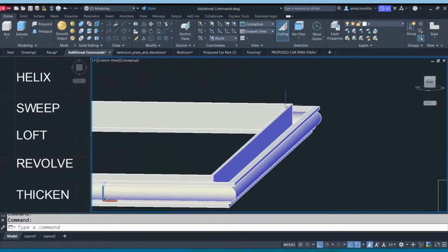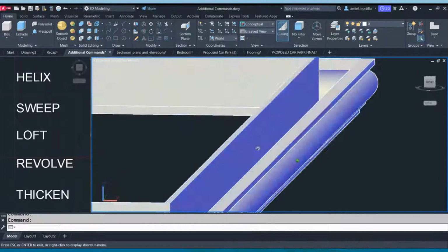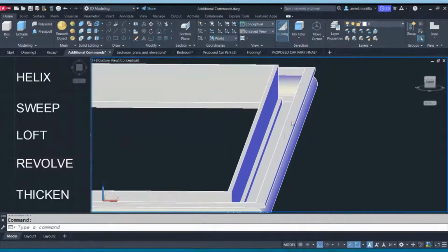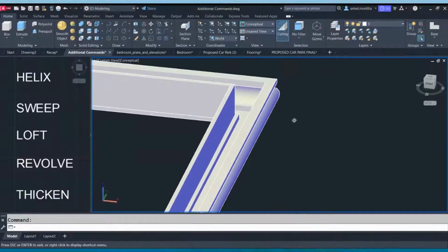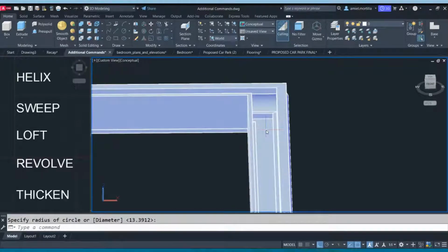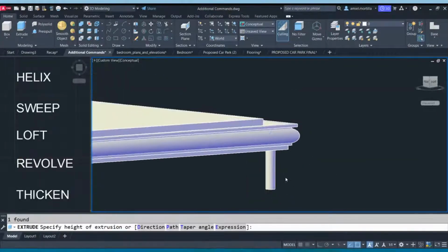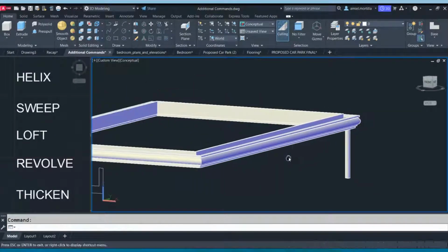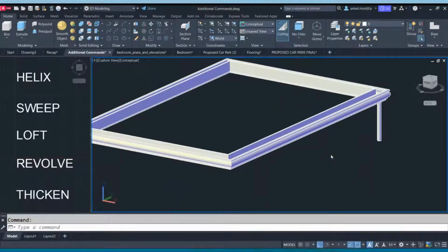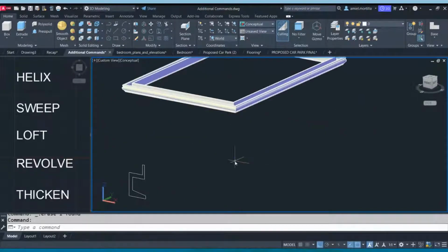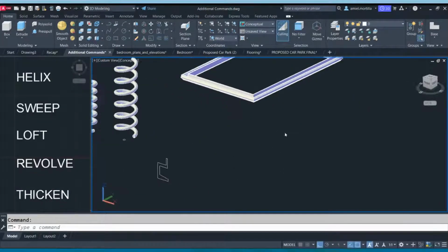For example, there is a roof here above, and this is your gutter, the roof drain. Then, for example, you want to place the drain there, PVC pipe, and there. So this is one example on how to use the sweep. A good example.